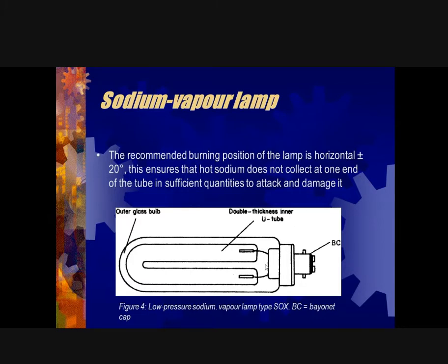So what they do is put the low pressure sodium type bulbs behind, and when it's ignited, it will shine through the printed part of the sign to indicate whatever they want to advertise, right? So it's utilized a lot in advertising signs and so forth. And it's normally mounted in the horizontal position. It can be at an angle of plus or minus 20 degrees, right?